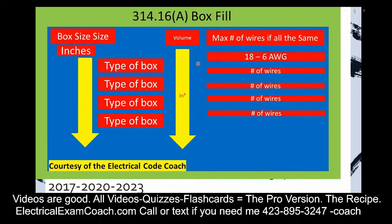And the reason it's cubic inches is because we have 3 different measurements. We have 4 by 4 by whatever the depth is. In this column, you're going to find the maximum that you're allowed to fill each box. Then when we come over here to the far right of the table, it's one of my favorite pieces. It's actually like a cheat sheet. If all of your wires are of the same size, you can use this part of the table and make it very simple on yourself.